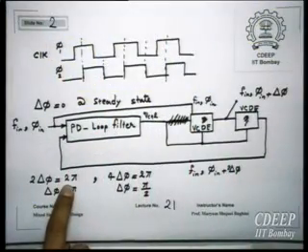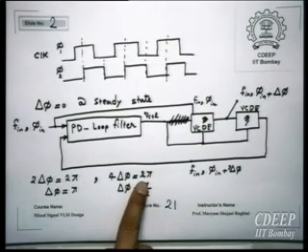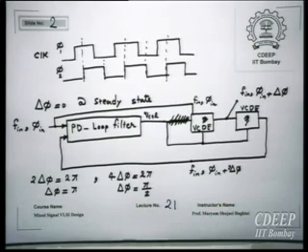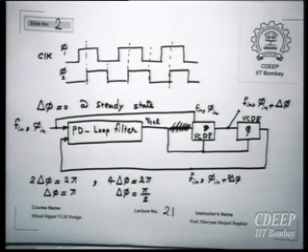That is the point. Suppose it is 4 pi, then instead of here, for example, 4 pi, it will be pi. That is one of the problems. Exactly. Like PLL, DLL has inherent ambiguity, meaning that it can lock in multiples of 2 pi also. But again, there are circuits which can control this phase shift. But inherently, yes, it's possible.